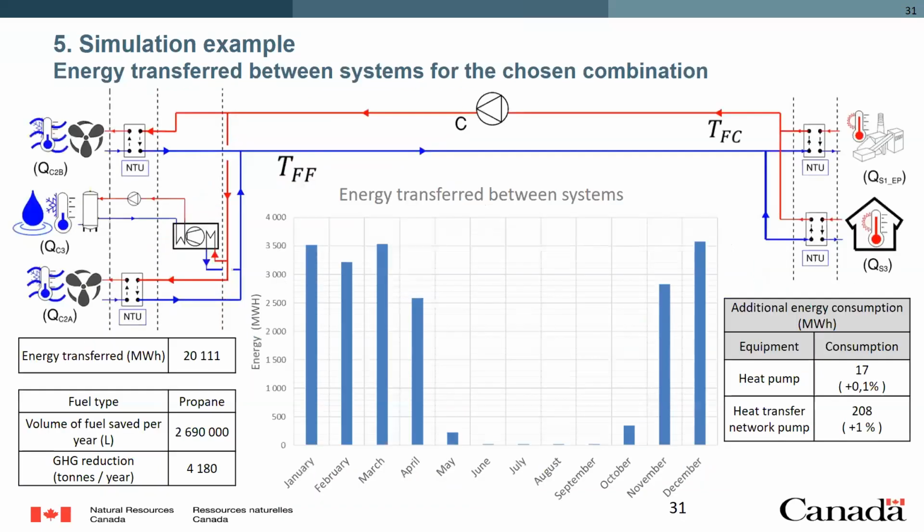And finally here, you'll have the total energy transfer, which, assuming that propane was the fuel used to generate the heating on the load side, would equate to so many liters of propane that would be displaced or saved during the year, and the same with the greenhouse gas emission reduction.